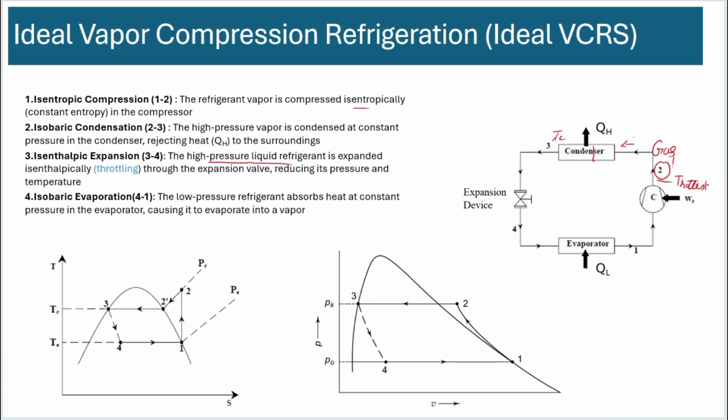Somewhere in the middle of the condenser, it starts forming liquid. Okay, so it doesn't have liquid in the beginning of the condenser. It gets colder, right? The temperature drops and reaches the two-phase region and starts forming liquid. So somewhere here it starts forming liquid, and by the time it comes out, based on the ideal cycle, it's all liquid that's going to the expansion device. Then outside of the expansion device, it's again liquid plus vapor. And the remaining one goes to the evaporator.